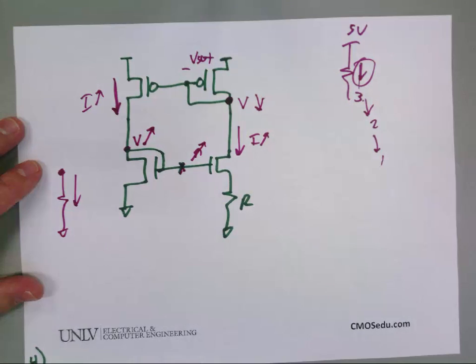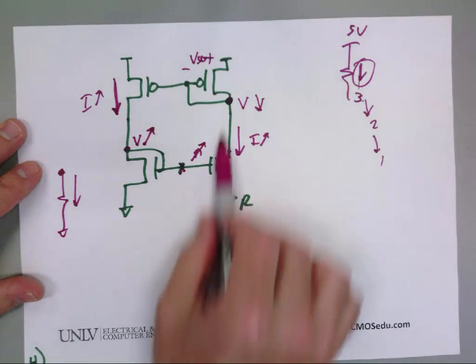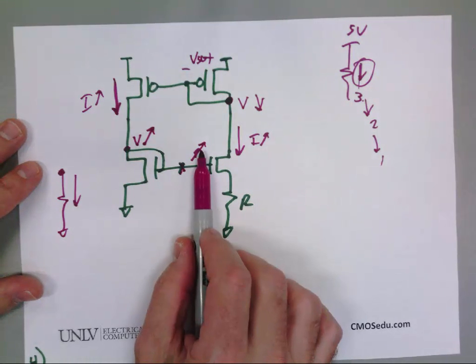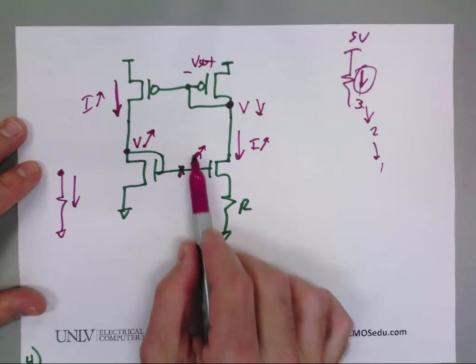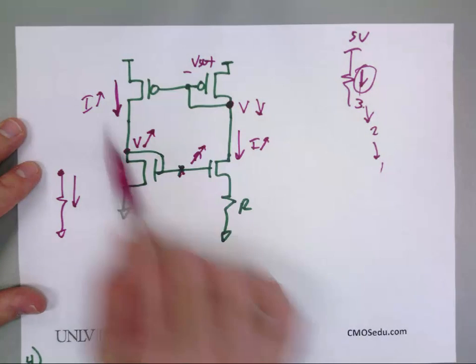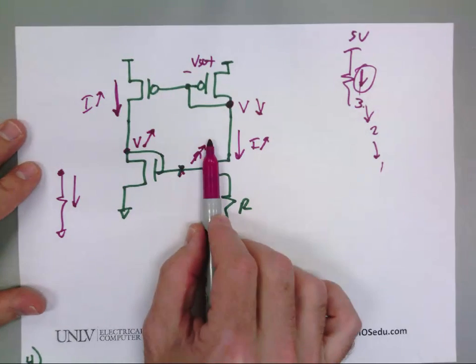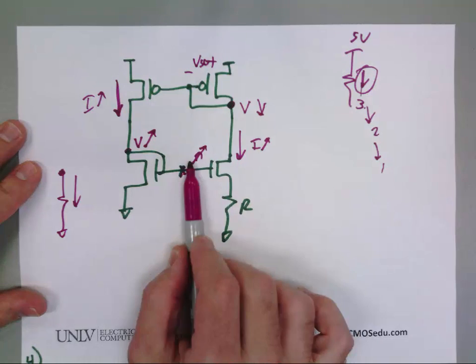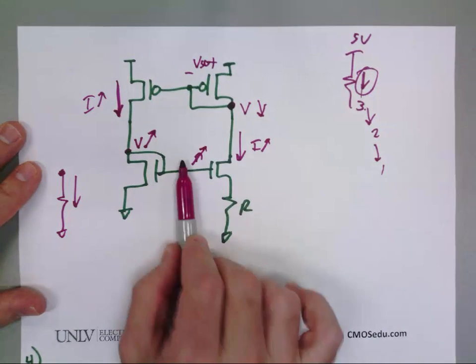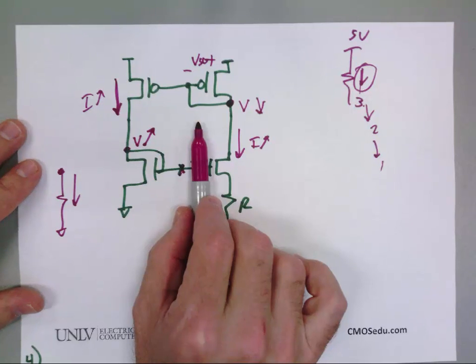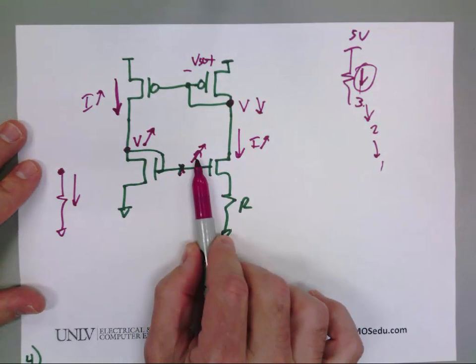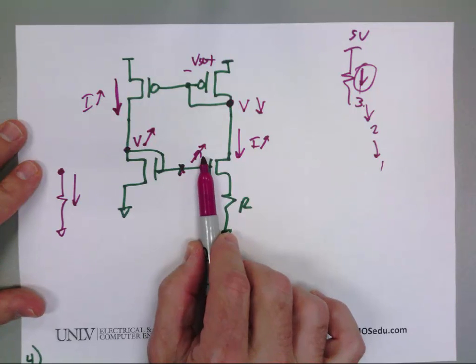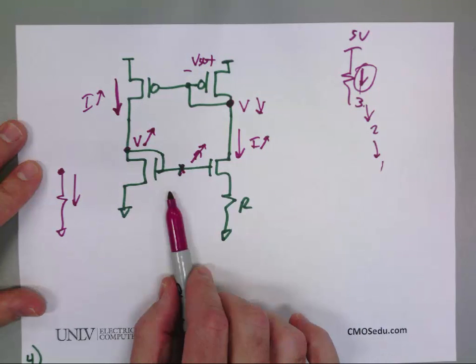But what I'm claiming is that the gain around the loop, even though it goes up, is not going to be greater than 1. If it was 2, this goes up by 1, then it feeds back around, and this goes up by 2, which increases this by 2, then this feeds back around, it goes up by 4, then it feeds back around, this goes up by 8. That doesn't work, right? So I have to make sure what I feed back is smaller than the signal that I have here, so that my positive feedback is less than 1.